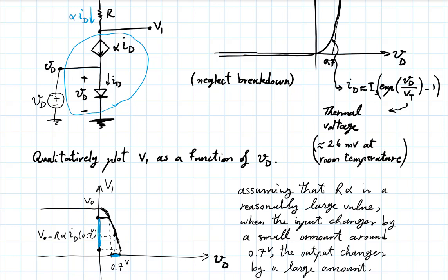So imagine if I think of the input voltage here as a bit of information, 0 or 1, depending on the amount of voltage. So let's say 0.5 volts is 0, and 1 volt or 0.75 volts is 1, right? If your input is 0, your output is 1. If your input is 1, your output is 0, right? You have changed. This is essentially how transistors operate in your logic circuits. Okay, and so that's basically a NOT function that I just described, right? By changing the input from 0 to 1, you're changing the output from 1 to 0, binary.